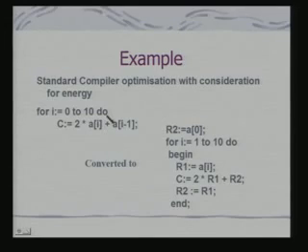Now, for minimizing the access I need to allocate registers. Let's consider that we have registers R1, R2, just like an ARM kind of scenario where I refer to registers by Ri. Here I am showing you one possibility where A0 is assigned to R2, and I am assigning AI, because this is 0 to 10, to R1. So R2 is actually containing AI minus 1, fine, and then I go through this loop.